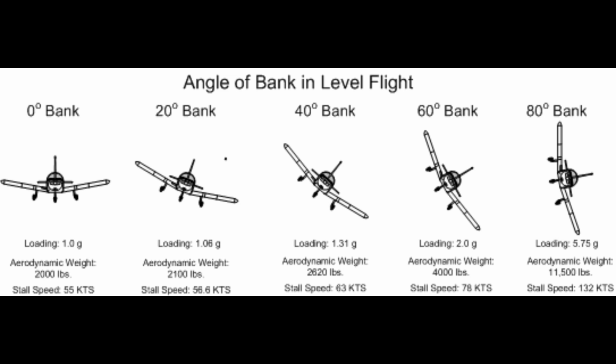The gust load factor requirements now in effect are substantially the same as those that have been in existence for years. Hundreds of thousands of operational hours have proven them adequate for safety. Since the pilot has little control over gust load factors, except to reduce the aircraft's speed when rough air is encountered, the gust loading requirements are substantially the same for most general aviation-type aircraft regardless of their operational use. Generally, the gust load factors control the design of aircraft which are intended for strictly non-acrobatic usage.